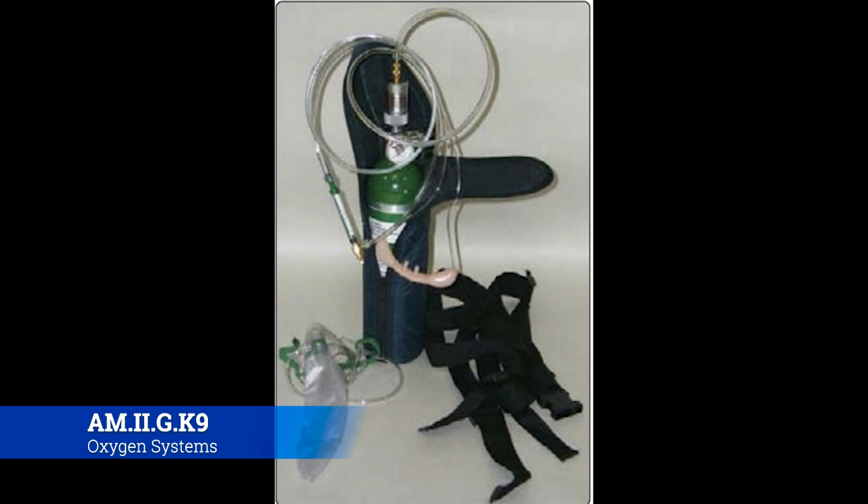Okay, let's talk about the anatomy of your oxygen storage cylinders. You have a cylinder itself that's usually made out of either steel or aluminum, but they could also be composite, which is good because it reduces the weight and decreases the chance of corrosion. Now, if you have a cylinder that gets below 50 psi, you want to immediately take it out of service and get it serviced. The reason being is that anything below 50 psi, water vapor can condense and form on the walls inside of the cylinder. If that happens and you're using especially a steel cylinder, you could get corrosion in there, and then you create a weak point in that cylinder, and you're susceptible to all kinds of problems.